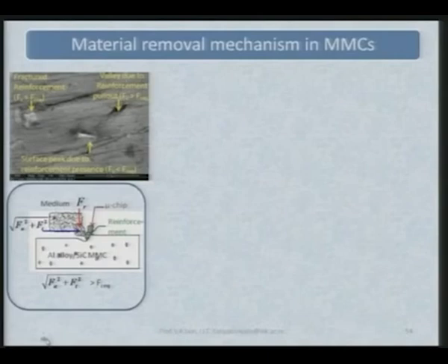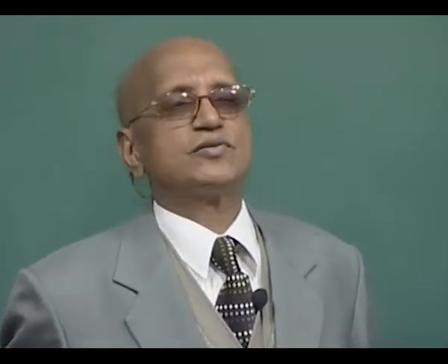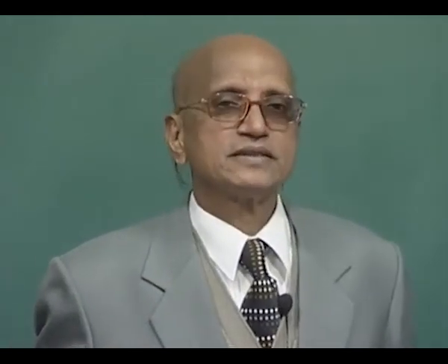As I mentioned, various mechanisms work in case of abrasive flow finishing of metals and alloys or non metals also, but in some cases when you are using metal matrix composites, where you are using solid particles of abrasives in the rest of the matrix material, in that case finishing mechanisms are different from the mechanism that is followed in case of uniform metals or uniform material.